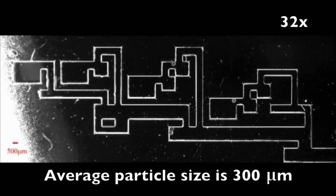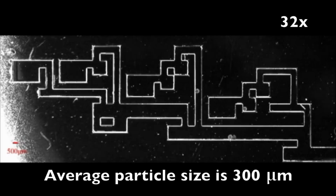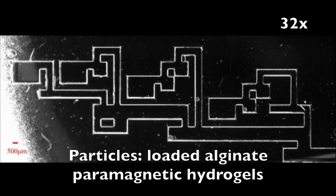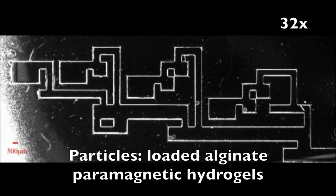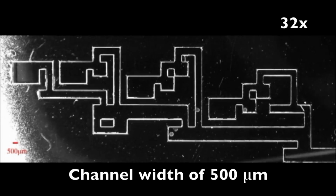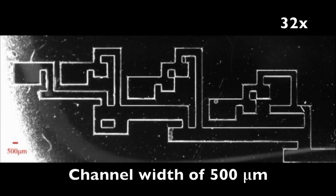Channels were formed from the SU8 photoresist filled with deionized water and 10% Tween 20. All microrobots used for these experiments were loaded alginate paramagnetic hydrogels, otherwise known as artificial cells. The global input is a clockwise up, right, down, left sequence.